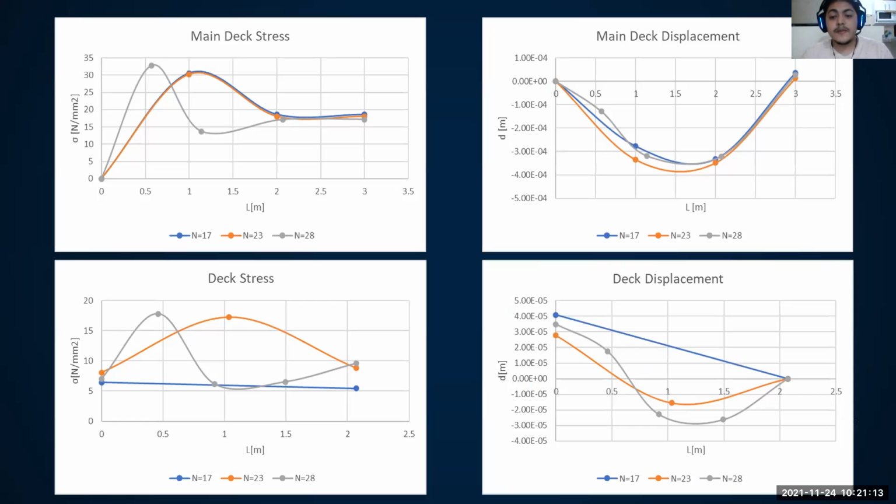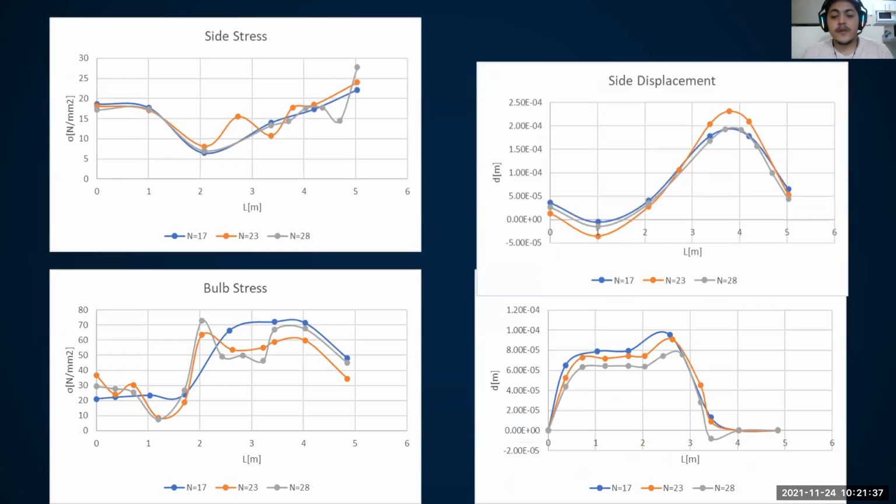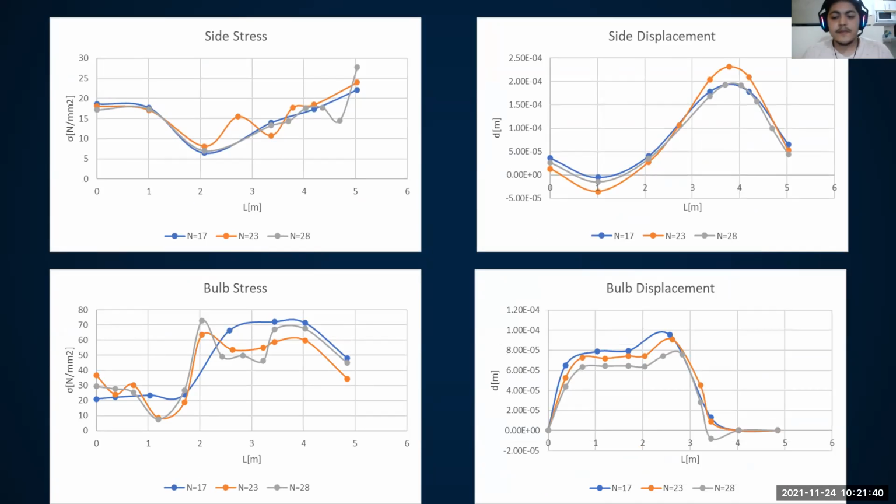Of the displacement, we observe the convergence of results because the distributed load is in the negative vertical direction. In the stress and deformation, we have different graphs because the number of elements analyzed is different: one element, two elements, and four elements respectively. We observe the convergence of results because it's the same, a load distribution in the negative vertical direction.